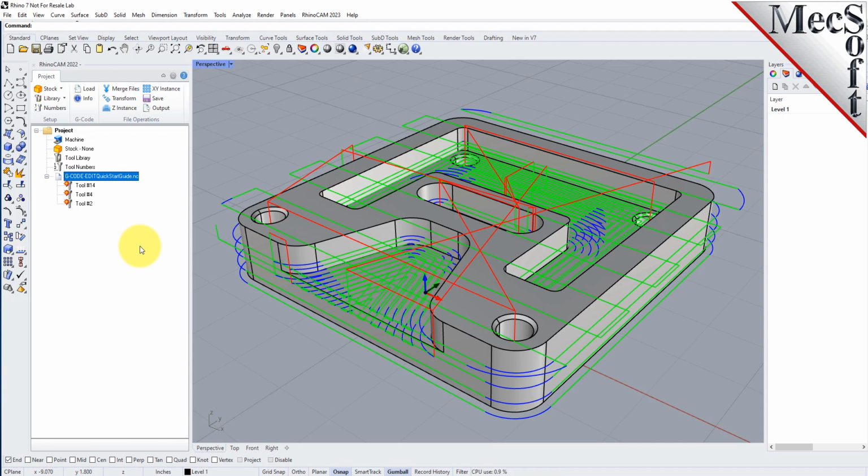Now, the reason they are flagged right now is that G-code editor is looking for a tool to match this tool number in your tool library. So it doesn't find it, so it flags them as dirty. And you don't need to resolve these flags just to open G-code files and do some quick editing on it. So you really only need to define your tools if you're going to do some tool motion simulation and some cut material simulation. I'll show you both of those.